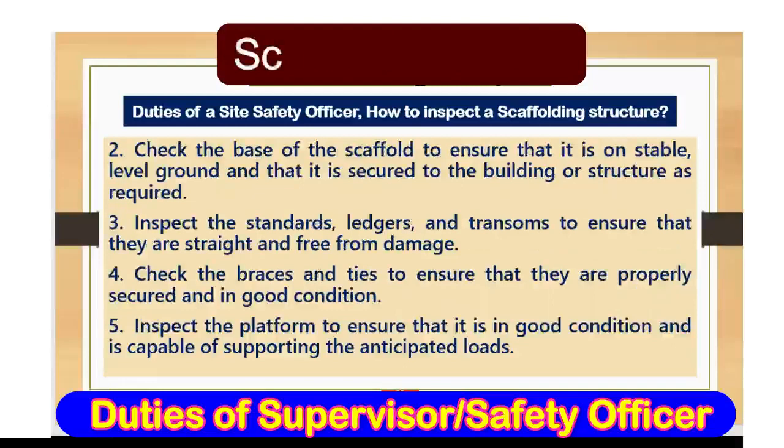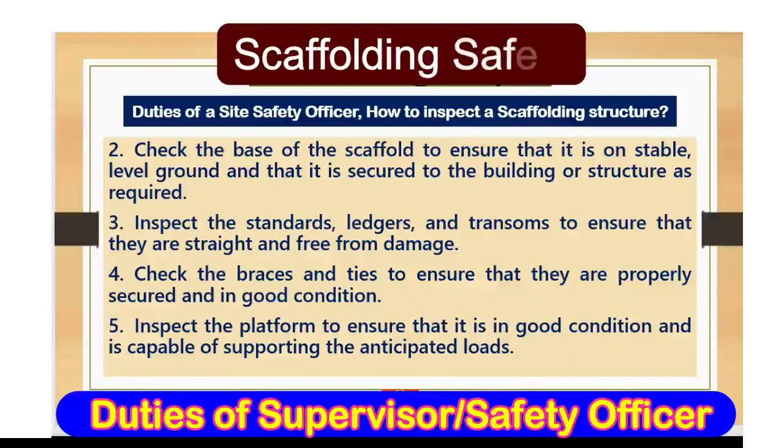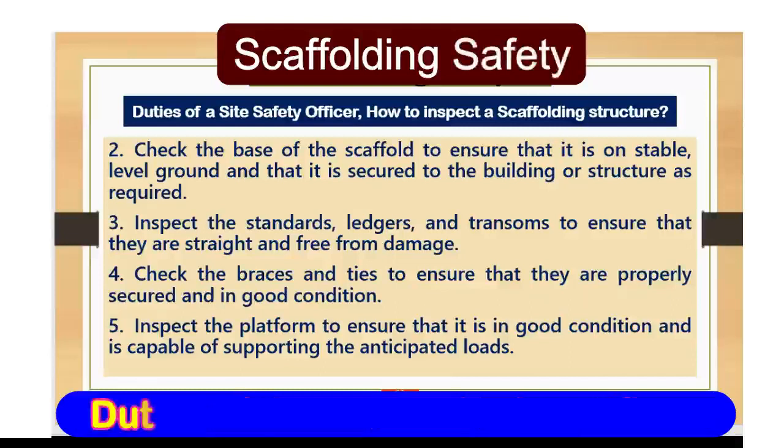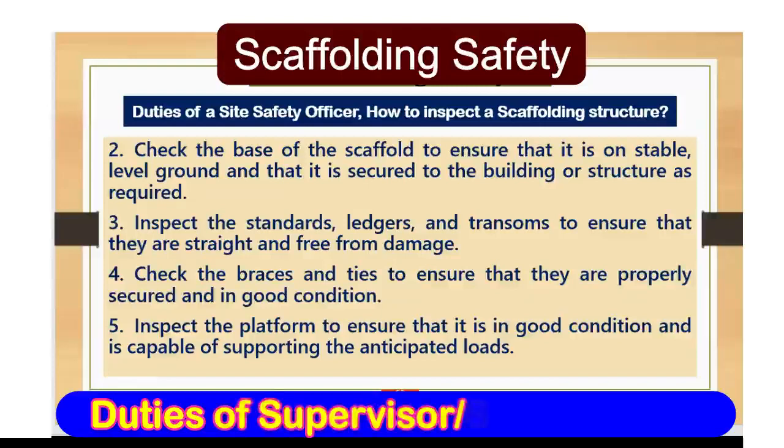Number two, check the base of the scaffold to ensure that it is on stable, level ground and that it is secured to the building or structure as required. Number three, inspect the standards, ledgers, and transoms to ensure that they are straight and free from damage. Number four, check the braces and ties to ensure that they are properly secured and in good condition.